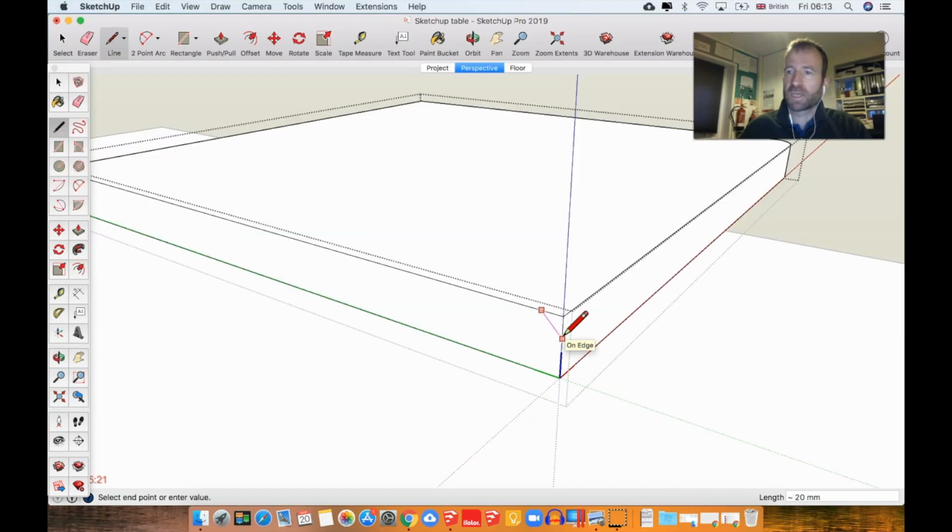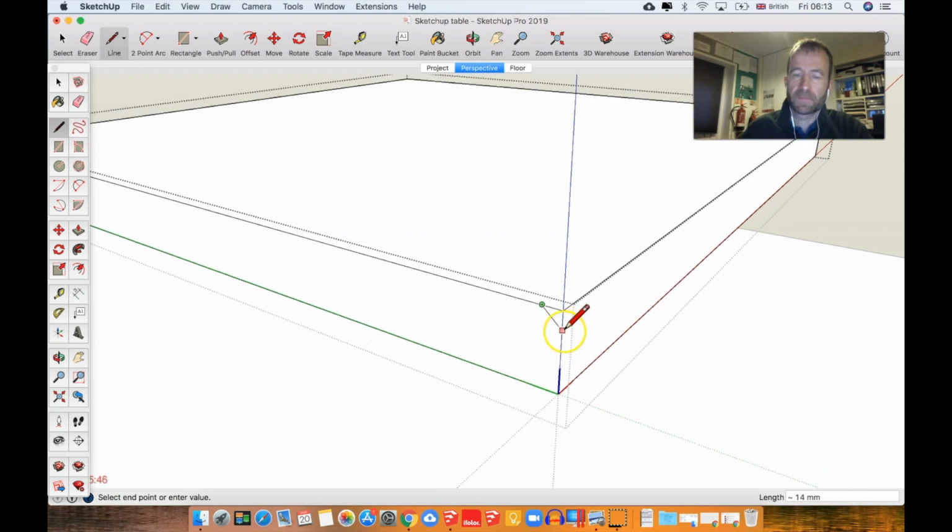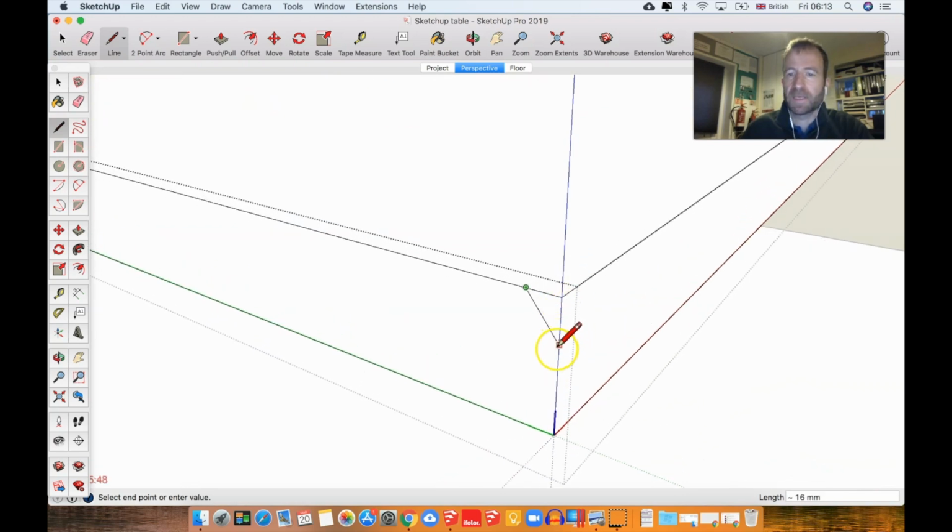I want this to be a precise size chamfer though, so I'm going to use the pencil as a sort of guideline, because it's quick and easy. Click there, come across, let's say we want that to come across 10 millimeters. That's given me an endpoint. It's effectively broken that line. So I can then come down again. But interestingly, it breaks its ability to put it at 45 degrees because it's coming off a broken line.